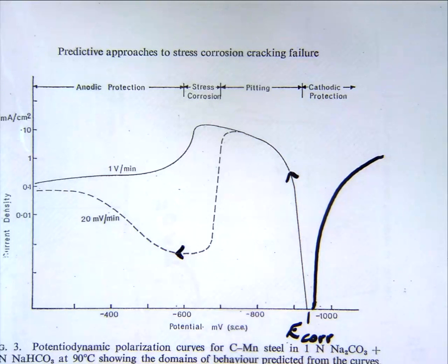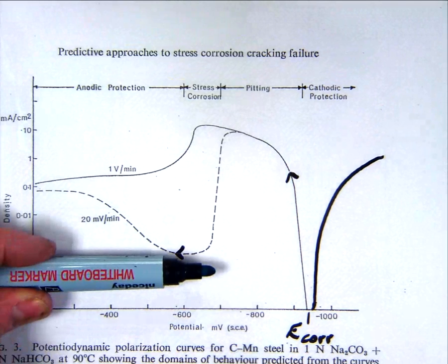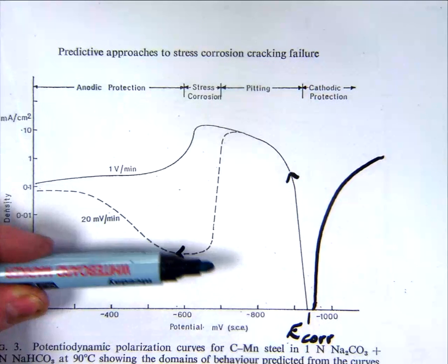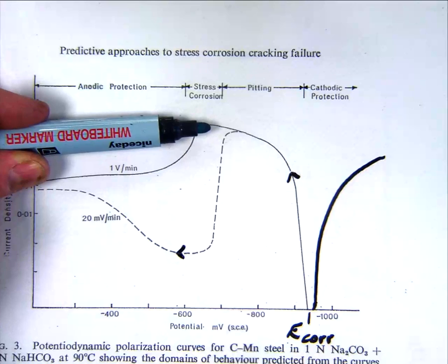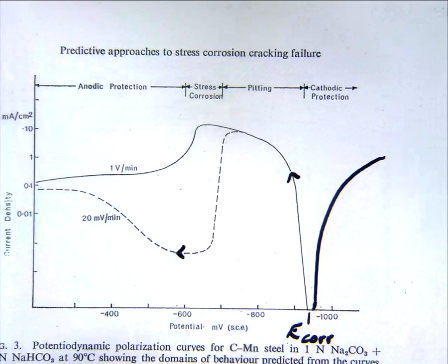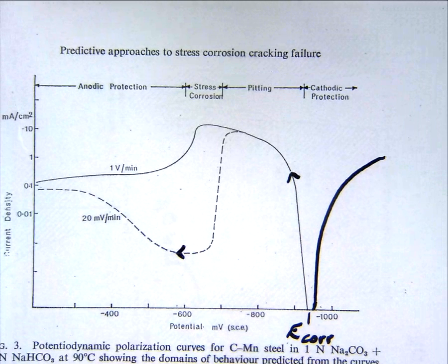Why would you have preference for corrosion at the root of the crack? Because that's where the stress is highest. That's where, most likely, the oxide film will be broken down, at the stress concentration. Just remember, there's some tensile stress here, whether it's residual or applied, at right angles to the crack growth.